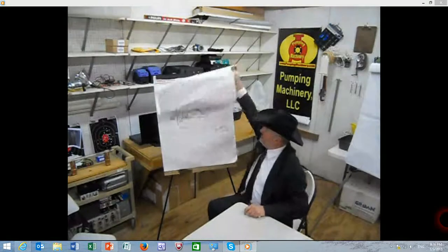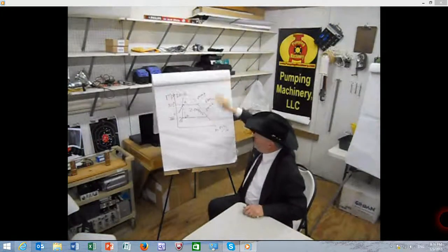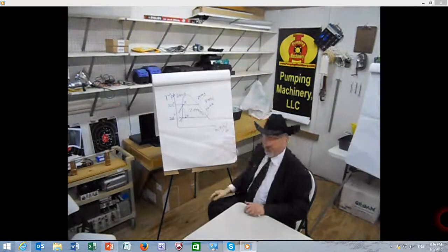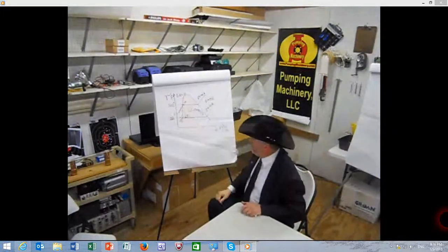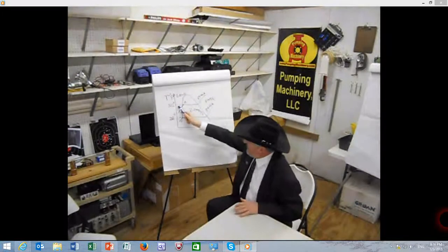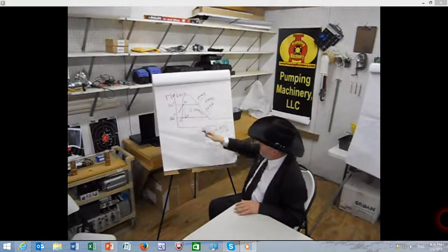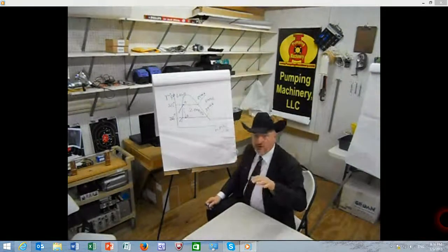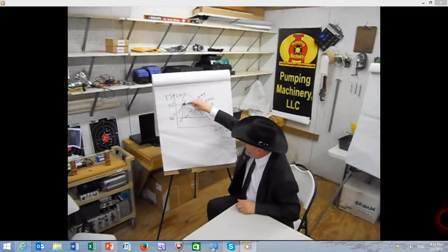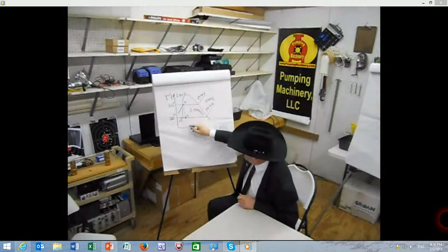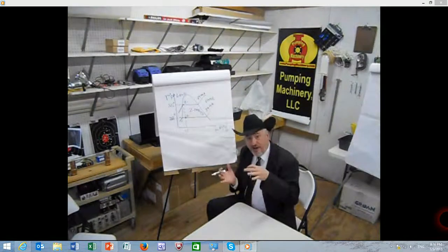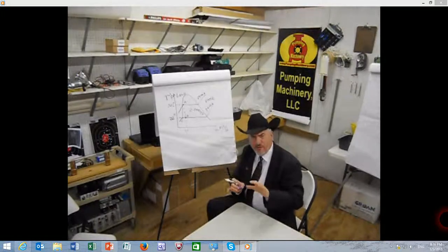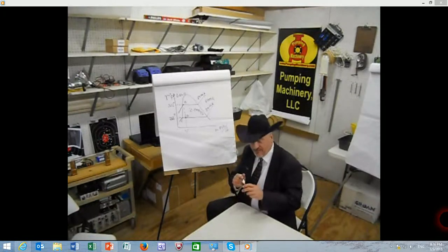Thermodynamically speaking, we have temperature versus unit volume, cubic feet per pound, and this is temperature in Fahrenheit. The liquid region is to the left, vapor to the right. Under the dome, there's a two-phase region. So when the pressure and temperature drop from the saturated point A at a constant volume, assuming the volume of the DA is constant, and that also can be questioned slightly, but for now, for simplicity, we'll assume it's a constant volume.